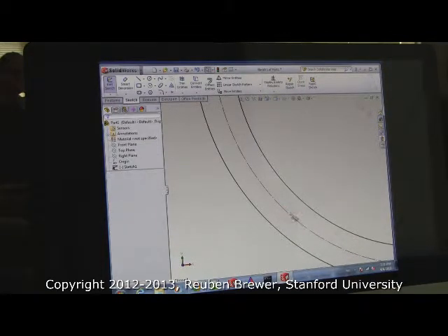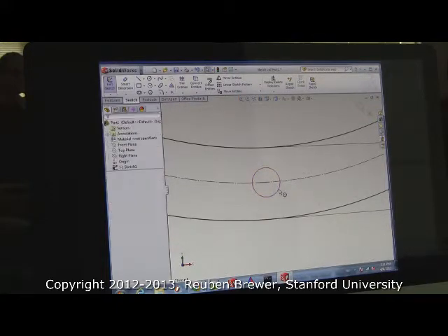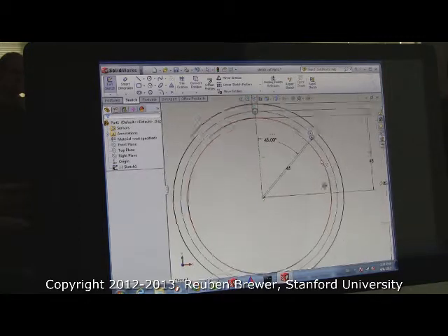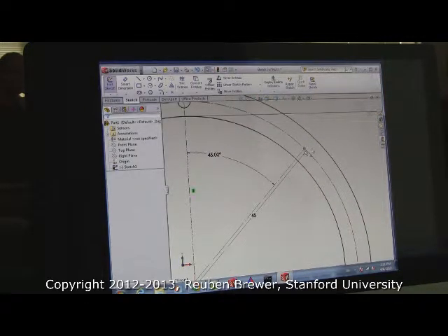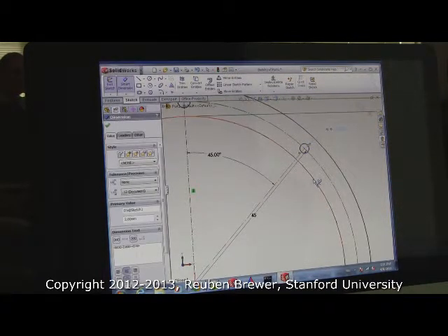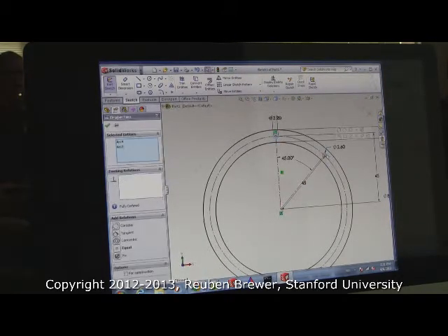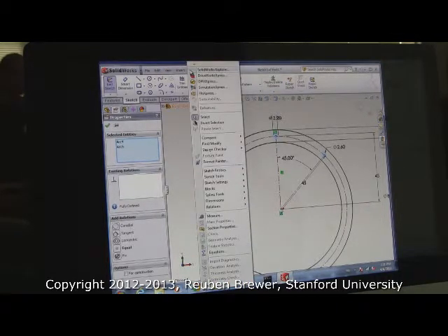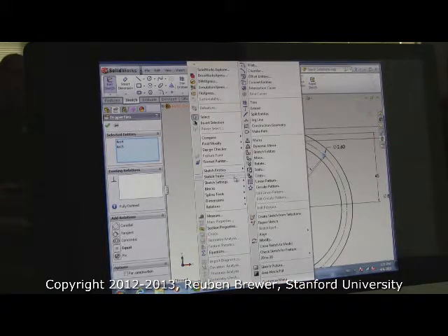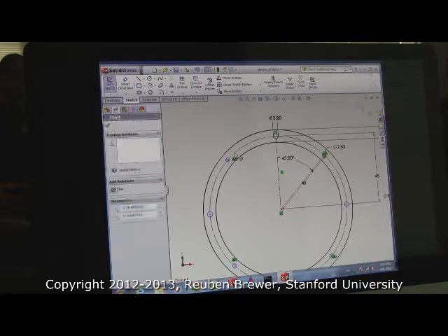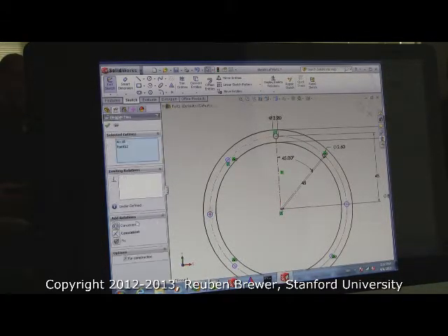Okay, so does anyone know why I was receiving an error? Because basically what had happened was my mouse clicked to do that pattern twice. So anytime in SolidWorks that you do something that doesn't make physical sense, such as put one circle on top of another, it will whine at you, and it should. It will tell you something like you have nested circles or you have intersecting models. Anytime you get that warning, it'll be when you press the button to go from the sketch and extrude it. That means you have an extra circle or squiggle or line somewhere, and you have to go back and fix it. So it's good it happened to me, because that was one of our next lessons.